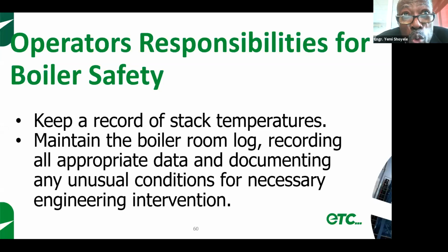If you do that, you will not suffer slow buildup and steam drop, because your consumer, the factory using the steam, is running, and whether you like it or not, if you are unable to meet up, then you will continue to drop. The first thing is you must have an adequate feed water temperature.